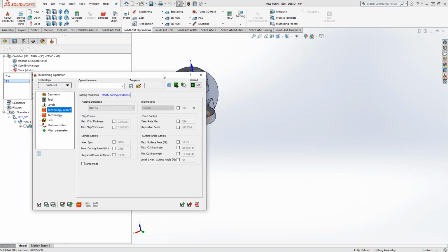But generally with metals, steels, aluminums, you should be able to just plug in your ultimate tensile strength and you're okay. But the machinability factor does come into play a lot when you're doing non-metals. We had some customers that were dealing with plastics, and because iMachining was developed for metals, the machinability factor really came in handy to dial it in even further for that polymer, for that plastic that they were machining.